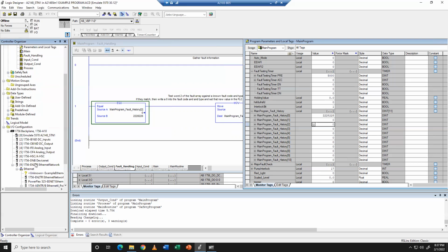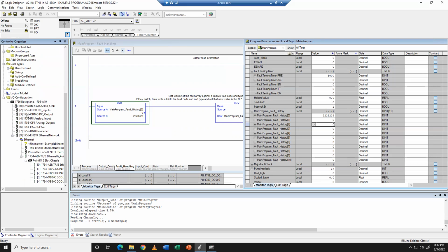So you might be able to clear some faults from communication modules. If you've got robots that throw faults for whatever reason, whenever they home or whenever they power off, or your controller is configured to produce and consume tags in a funny way that periodically have issues.